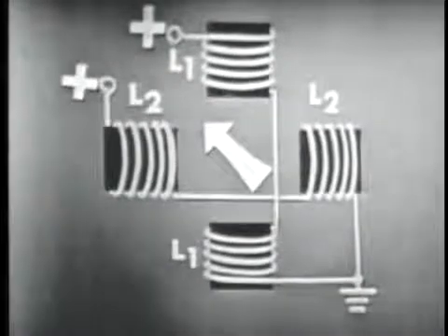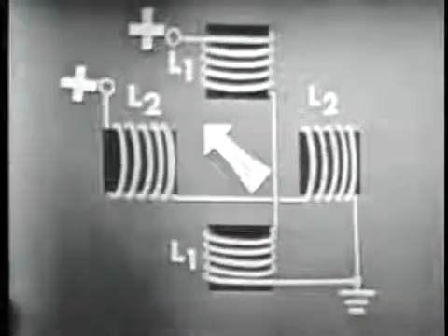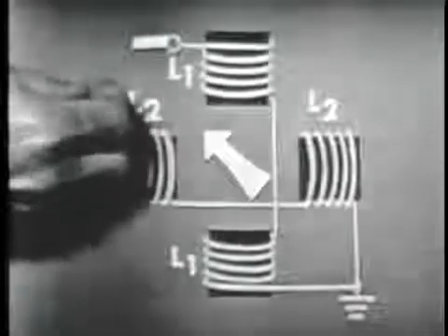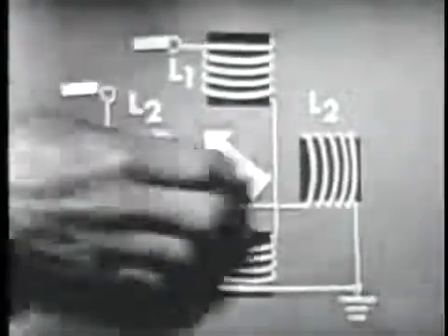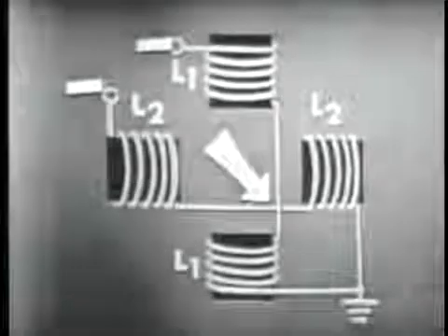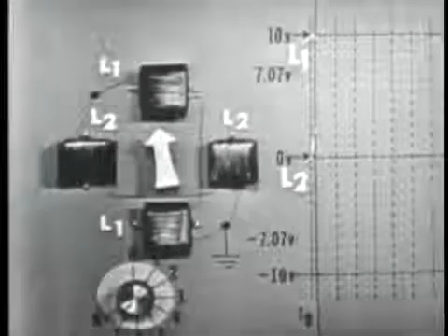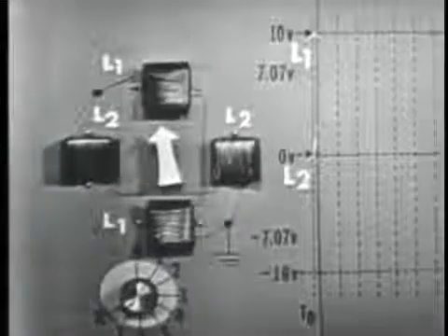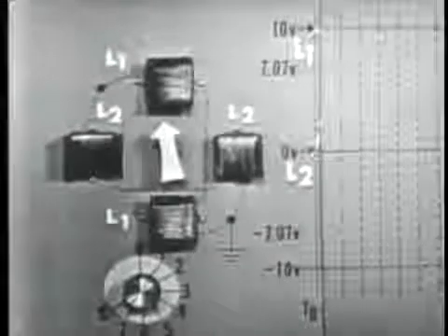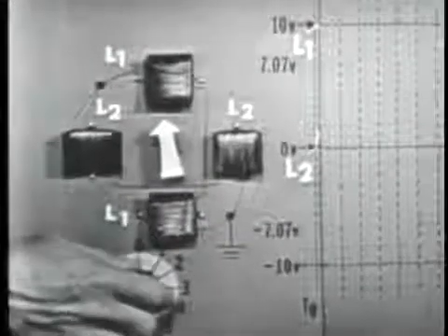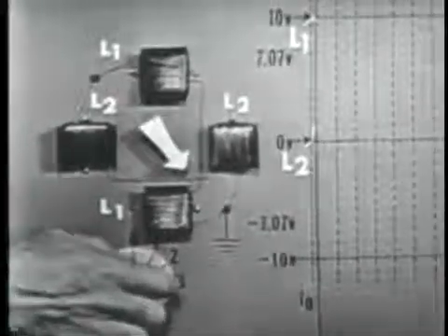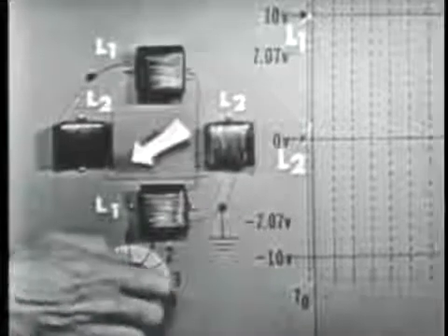And of course, if we reverse the polarity on both coils, we would reverse the direction of the magnetic field. We're going from positive to negative again, like this. Exactly opposite polarity, and we reverse the direction of the magnetic field, causing it to move down and to the right. Right. Well, that essentially is what we're going to do in this demonstration. Simply supply voltage with the proper polarity to cause a magnetic field to rotate 360 degrees in a clockwise direction. Right. Now, we could just as easily produce counterclockwise rotation by reversing the direction of the windings on L1 and L2, but we chose clockwise.